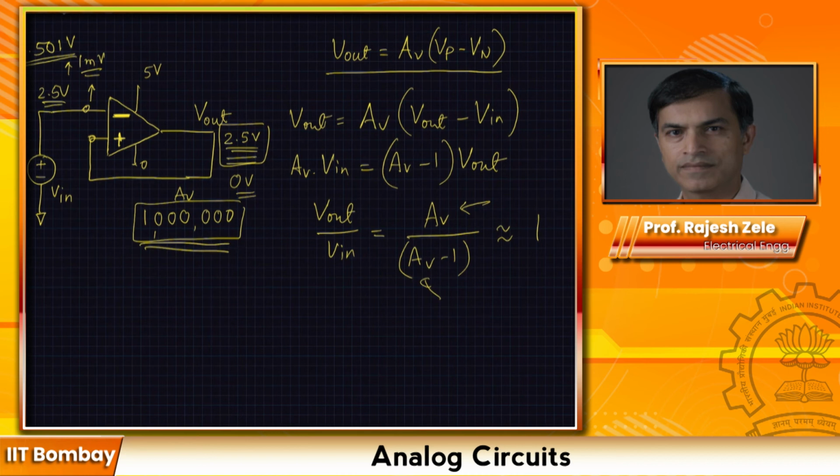The key point I'm trying to tell you is that the amplifier is not really behaving like the equation that we have brought out, because in this equation we just proved to ourselves that the amplifier is actually a unity gain amplifier. Basically V out is equal to Vn, but that's not what is going on. And the reason for that is something called feedback.